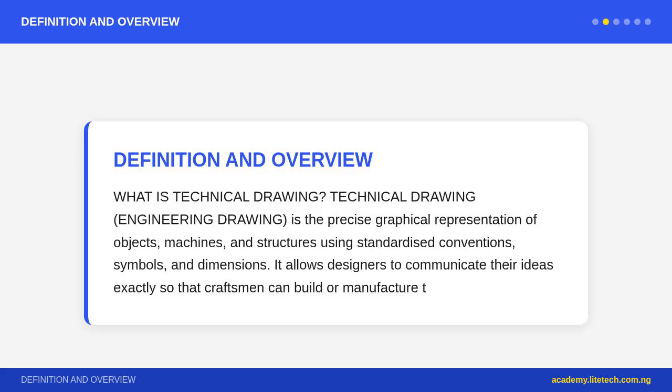Protractor: a semicircular instrument marked 0 to 180 degrees, which measures and marks angles that are not multiples of 15 degrees. More drawing instruments. Compass: a metal instrument with two legs, one holds a needle point, the pivot, the other holds a pencil lead. Used to draw circles and arcs of accurate radius. Adjust the compass to the required radius, place the needle point on the center, and rotate the pencil leg to draw.